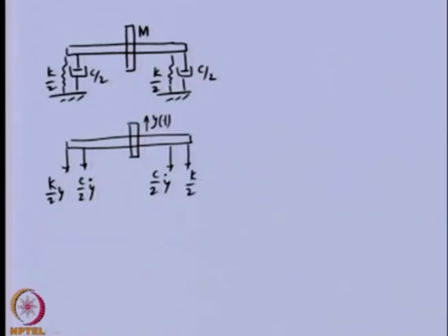Here also, because we have considered the bearing as symmetric, and inertia force will be opposite to this. So, the equation of motion, if we balance all the forces and moment, will be minus k y, that is from both the bearings, minus c y dot from both the bearings. There is no unbalance, let us say. So, external force due to unbalance is 0, which should be equal to the inertia term. So, basically this equation is